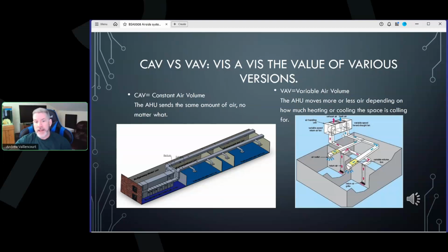I'm going to turn my fan down and only send 1,500 CFM of air instead of 5,000. We don't need 5,000. We don't want 5,000. So you're not getting 5,000. So that 3,500 CFM of air, you no longer have to move it. Now remember what I said earlier about the affinity law. I've just reduced the airflow by 3/5, a lot, 65, 70%.